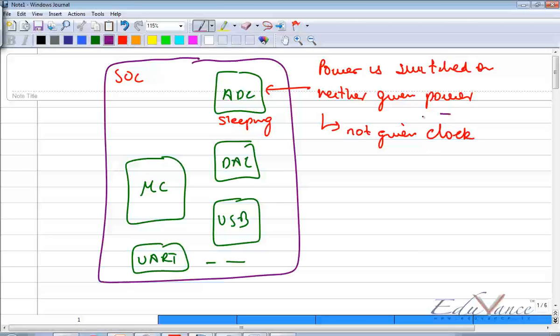Now clock plays a very significant role here. Before that, I'd like to mention that the clock component on the SoC has already been woken up, since the clock module has to supply to the microcontroller. However, the clock inputs to the interface ICs have not yet been activated.